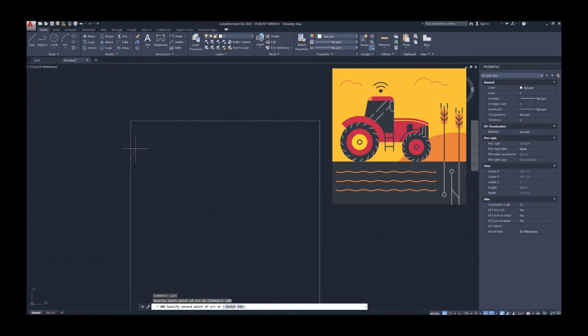So next I'm going to choose the second point of my arc. Usually that's about where you'd like the middle to be. So I'm going to choose this endpoint, okay? And then I'm going to this extension, okay? Now that I've chosen here, I'm going to choose the extension, if I can grab that line again, yeah. So that is going to be 100, okay?